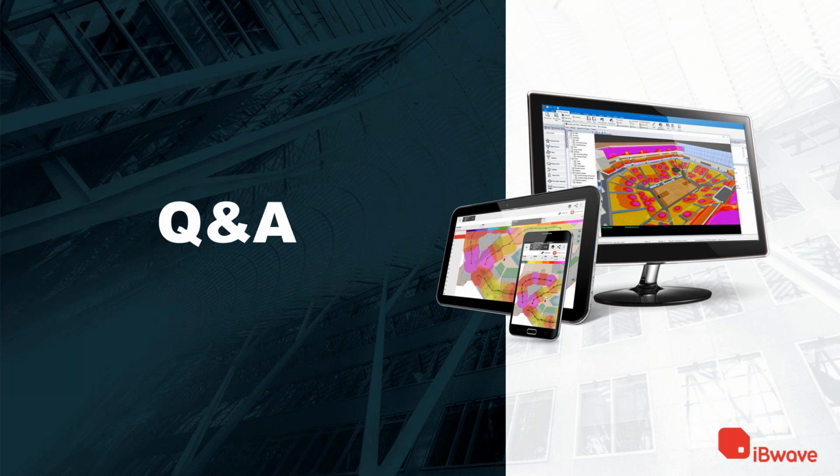Okay, go for it. Since CBRS is a new band for LTE, so far LTE was used only up to 2.6 gigahertz, and in some rare cases on 5 gigahertz for LTE-U or LAA. Any DAS equipment already installed may not work since it's limited to 2.6. You need to check the cabling, the antennas, and your DAS components. If it's an active DAS, for example, you need new RF cards.